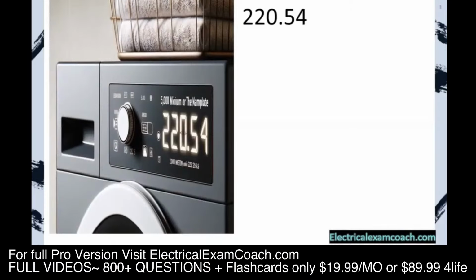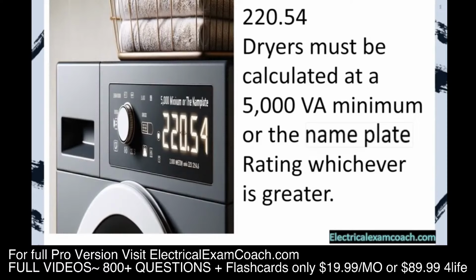Section 220.54 lets us know that dryers must be calculated at a 5,000 VA minimum or the nameplate rating, whichever is greater. Now, let's learn what a nameplate is.